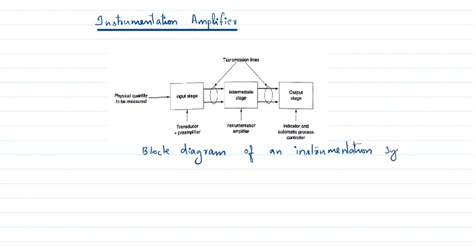Usually the main types of transducer are the thermistor and photo cells. We generally use the thermistor where the physical quantity that we measure is temperature. As temperature increases, there will be a change in resistance. For a thermistor, as temperature increases, resistance decreases, a negative temperature coefficient. Another one is photo cells, where the intensity of the light falling on them affects the resistance of the circuit.